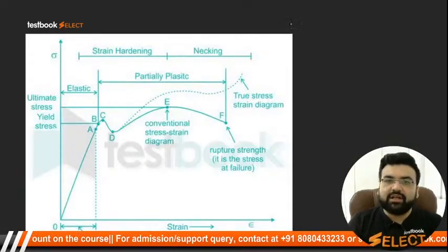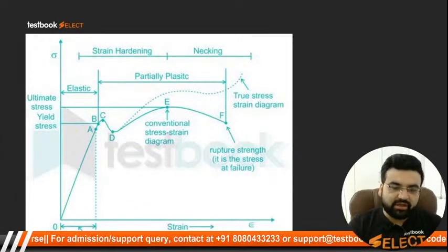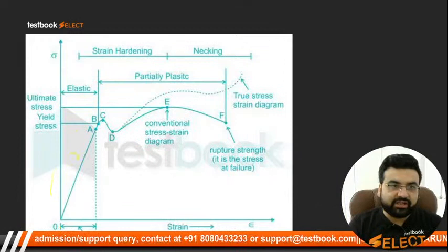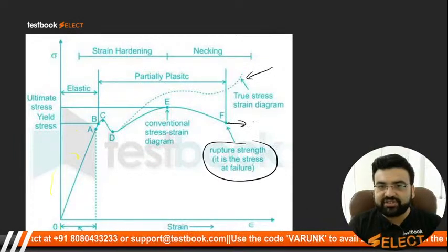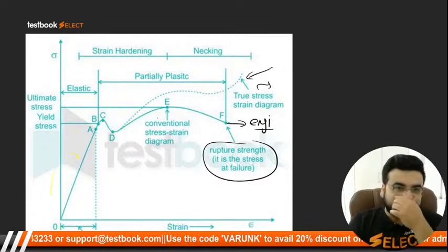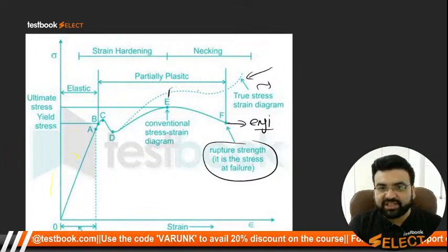So this is what the true stress versus strain curve is. Let me take a different marker here, then you will get it much more clearly. See here students, this is the true stress versus strain curve, this is the rupture strength, and this is the engineering stress versus strain curve. This is engineering and this is true, right? So after necking, this particular portion just keeps on increasing.